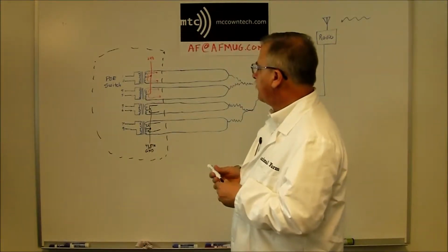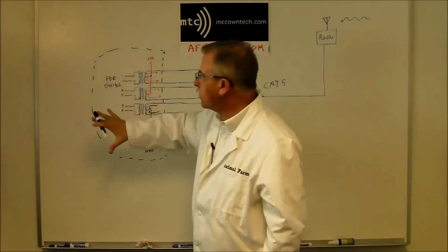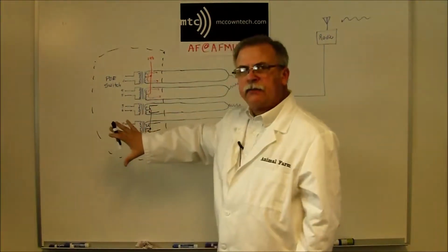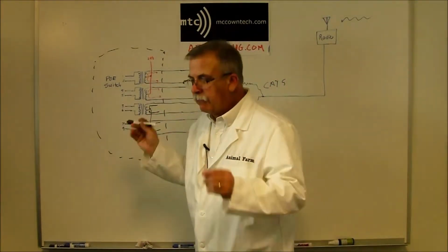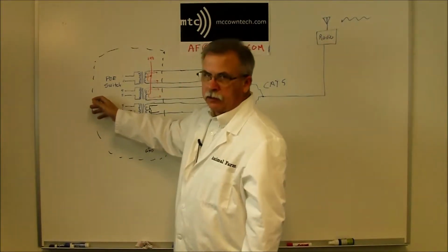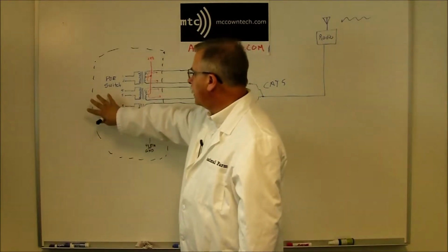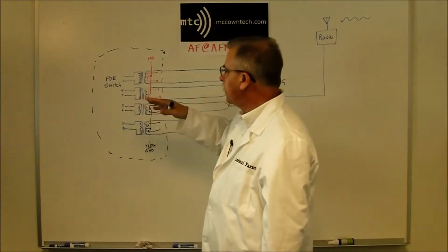And so you've got the data coming from, say, the switch integrated circuit inside the device, and it comes out here and hits this transformer. As far as I know, all Ethernet products have a transformer coupling the digital signals inside the switch. Actually, in the case of Ethernet, it's a lot more than just a simple digital signal.